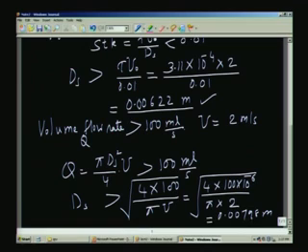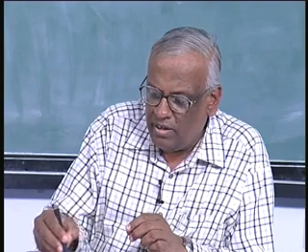So, this is an 8 millimeter tube and this is a 6 millimeter tube. We would have to choose the larger, because this requirement is more important than the other. Therefore, ds is chosen as 0.008 meter, or 8 millimeters.